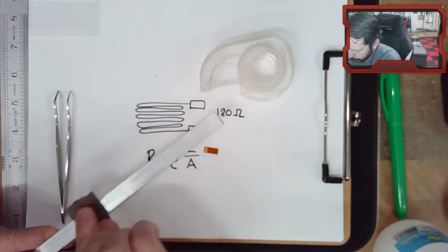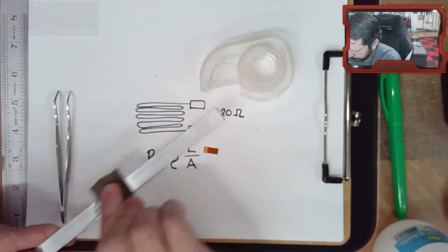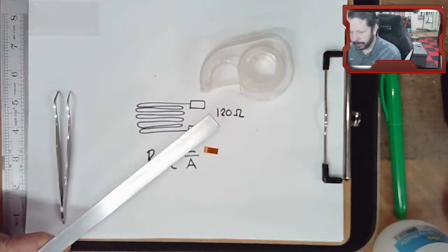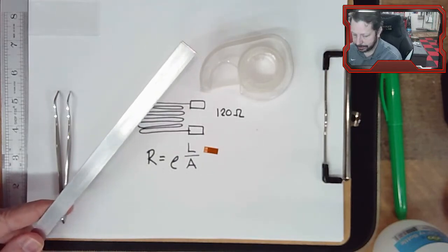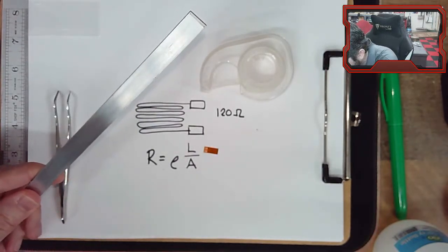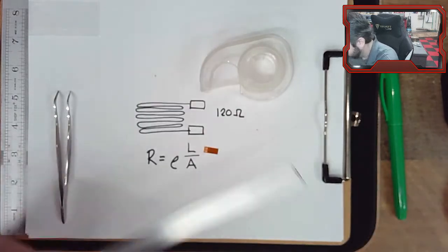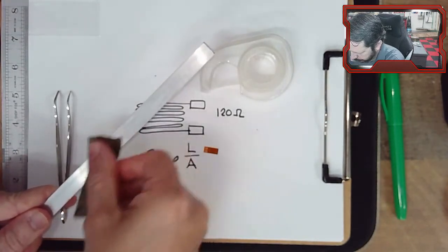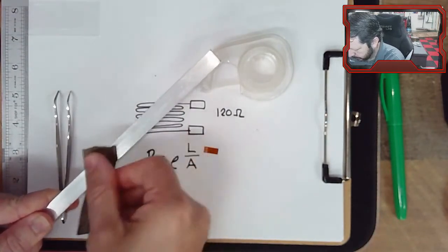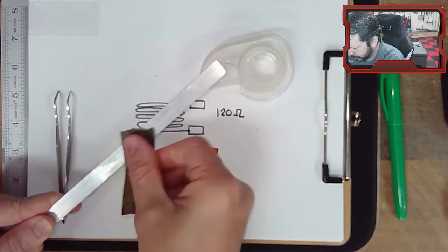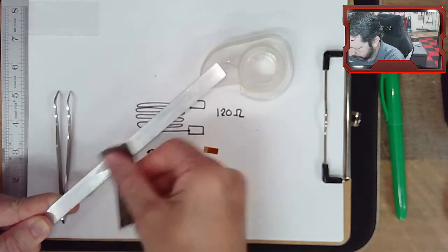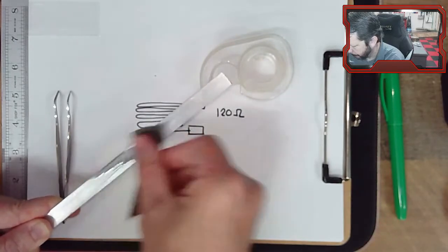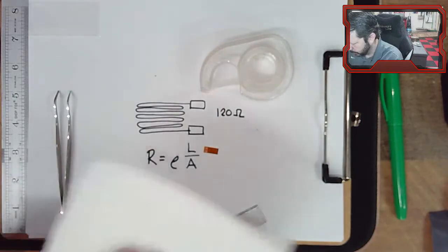Oh, one other thing, you need something to wipe all this stuff off with. Now there are actual cleaners and activators that you can use for this, but I'm doing what we can do right now. So we're just trying to get it clean. I'm not trying to sand it smooth or anything. I just want to get it clean where I'm going to mount this strain gauge. That's probably going to be plenty.